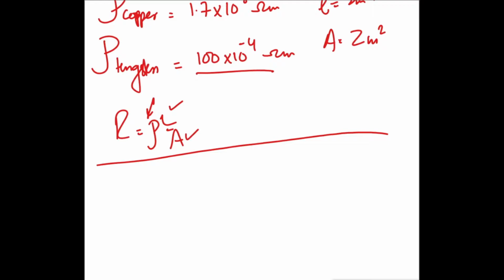And in terms of physics and physical reality, that gives you the idea, as a designer, as an engineer, as a scientist, what metal you are working with. For example, in certain cases, the design requirement will be, let's say, they want a 10 ohm resistor made out of tungsten. So it will be at your discretion what cross-sectional area you use, what length you use based on the application, right? So these are the formulas that you will use to design the respective resistor that is going to do the job which has been demanded from you, right?